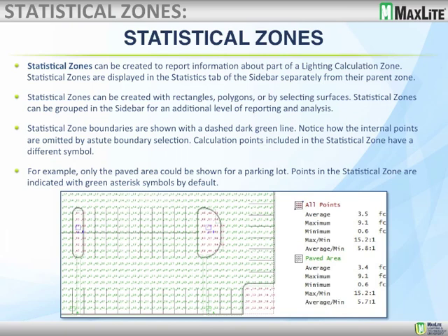Well, there's a national code, which is IES, and then there are local codes, which cities and townships take into consideration. For instance, say path of egress for emergency. In the LA area or even the state of California, they require 1 foot candle minimum for a path of egress. Now, the rest of the nation follows 1 foot candle average. So there's a difference. Average being the entire area, you calculate across it and get an average of 1 foot candle. Whereas in California, the lowest point anywhere within that path is 1 foot candle or above.